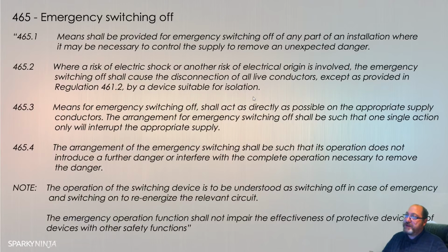And that's emergency switching. Now, we've just talked about the purpose of selecting switching for protection, but we've also talked about the types. We have isolation, mechanical maintenance, functional switching, and emergency switching. Now, with that in mind, before we finish this video, we just want to quickly look at section 537, which is on page 181, and there is a table, table 537.4, titled Guidance on the Selection of Protective Isolation and Switching Devices.